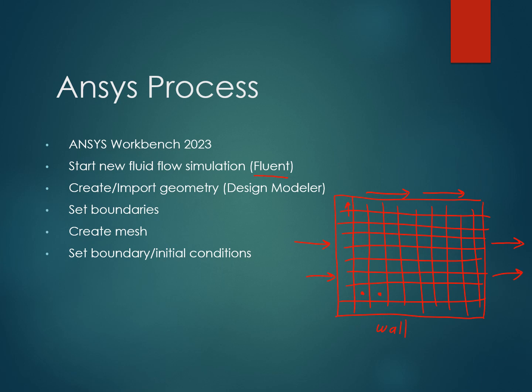So this is in terms of our fluid velocity going in, fluid pressure going out, and what initially our conditions are for this whole geometry. Then we'll actually run the simulation, see how that begins to converge and finalize on one correct answer, and then we'll analyze those results in a separate program called CFDPost.